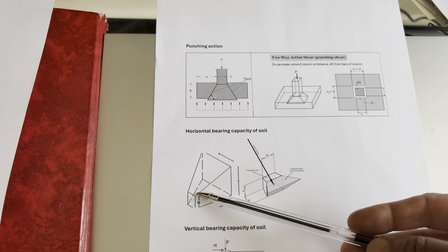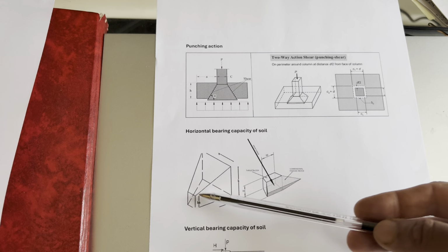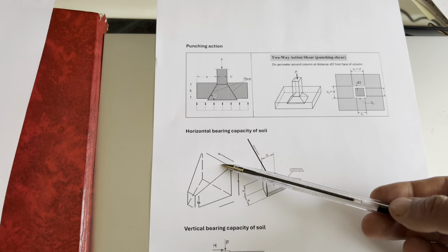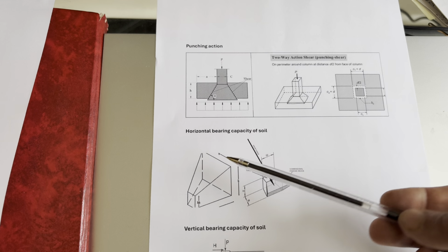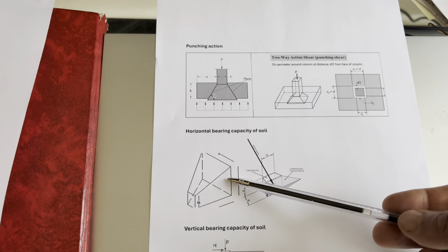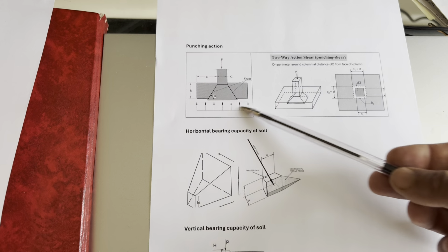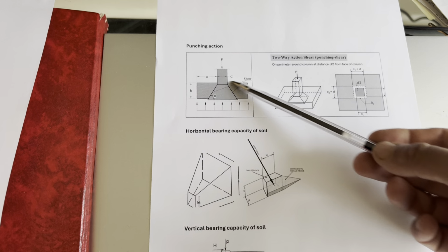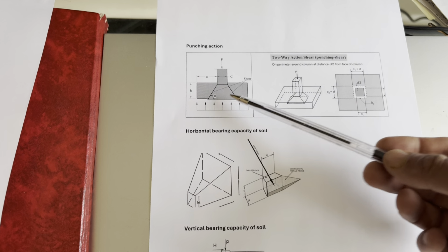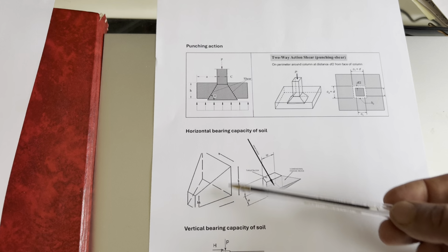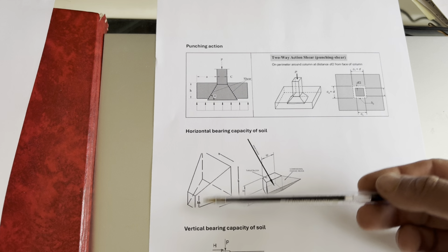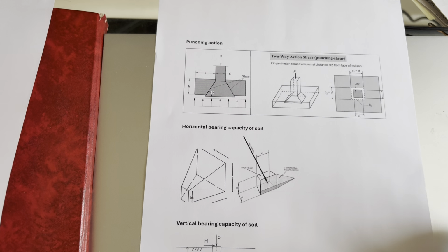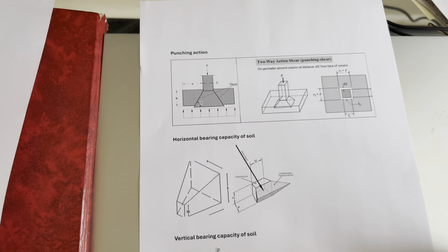First, you go for unfactored load for serviceability, and transfer the load to the area behind the block. If it is under the bearing capacity of the soil, we say it's enough. The other part is that we increase the thrust load, actually we go for ultimate load, and we check with the punching shear of this unreinforced concrete block. If it's okay, we say the unreinforced concrete block is strong enough for serviceability to transfer the load to the soil, and also itself can take the loads. Otherwise, we need to put some reinforcement.